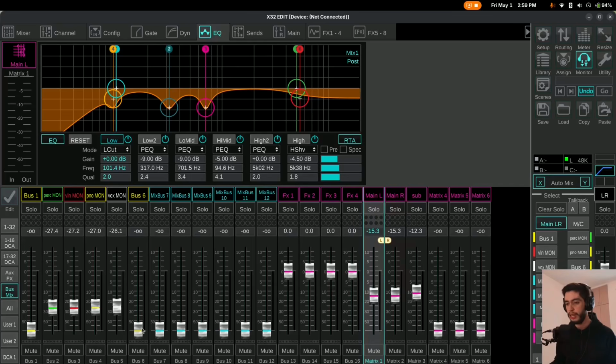So if I'm turning up the master fader of the bus, and right here it's starting to get uncomfortably loud, I might still turn it up like 3 or 4 dB in case the musician really needs that extra volume when they are all playing together, so that I'm not stuck. So like you can see here at minus 30 it was plenty loud, but I still turned it up a little bit because singers can never hear their voice despite it being the loudest thing on stage.